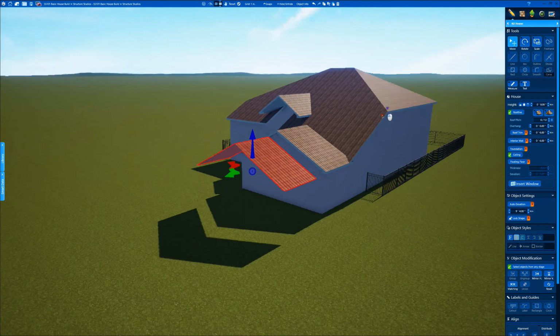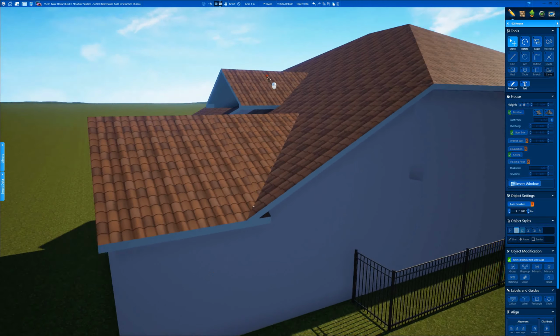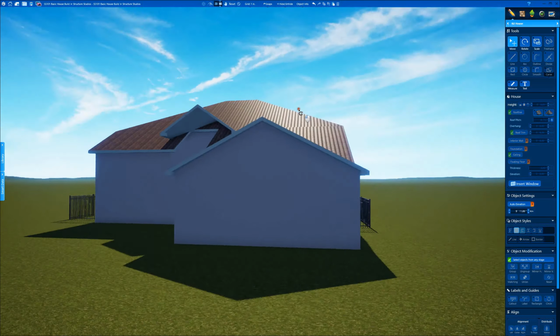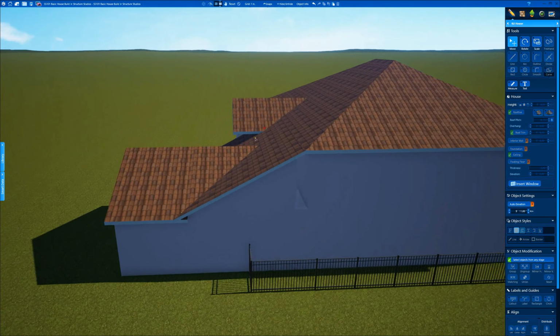Here's a connection here. So what I did was I turned off the overhang, I turned off the roof trim, and then just made a filler piece. Now I'm just going to grab it because I'm snapped, and there it is. Look at that, seamless, and I don't see the roof line through the wall. So that's how you do that section.